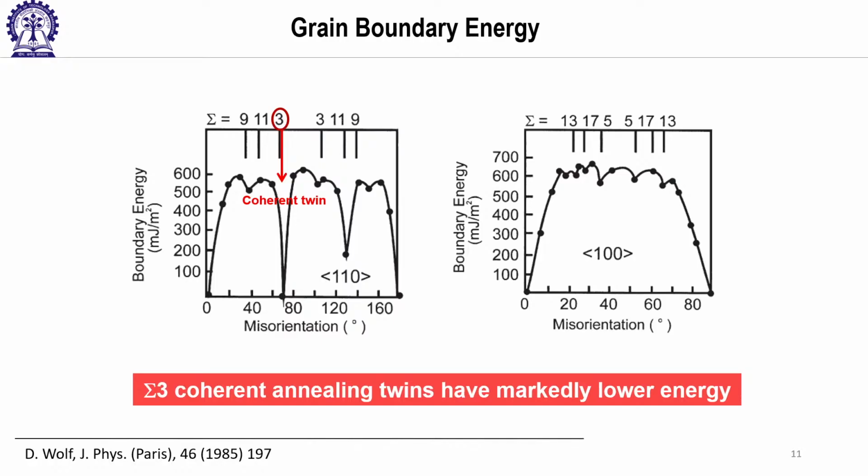Yes. I purposely did not discuss this because then the grain boundary plane comes into the picture here. You can see that both are sigma 3, but they have contrasting energy. In both, out of 3 atoms, 1 atom is coincident, so both should have lower energy. But then why the difference?